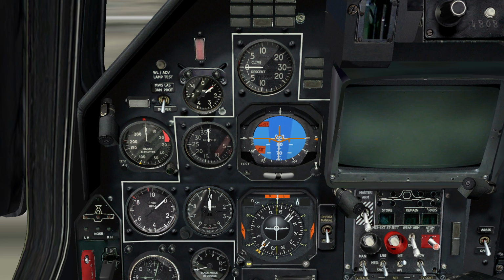meters. The vertical velocity indicator, VVI, measures the aircraft's rate of climb or descent and also is used to help maintain level flight. The Rotor RPM Indicator displays the tachometer measurement of the rotor's revolutions per minute, RPM, as a percentage of its maximum value. The Airspeed Indicator displays the aircraft's indicated airspeed.